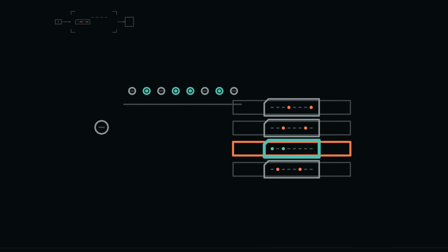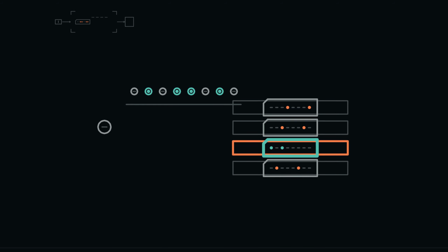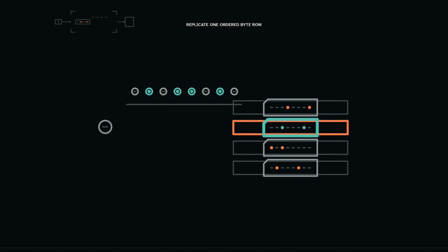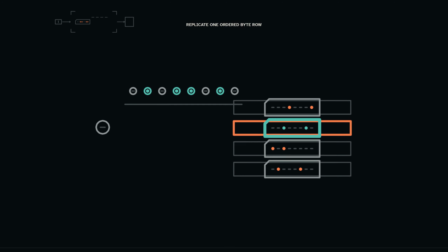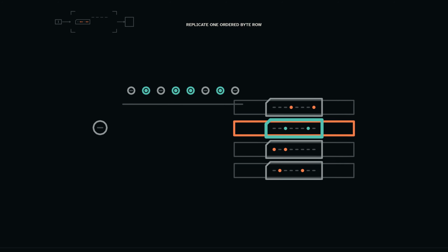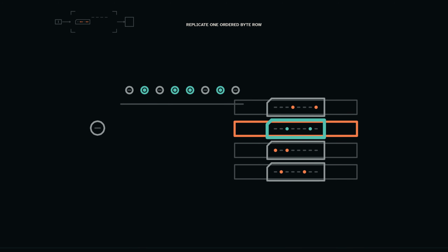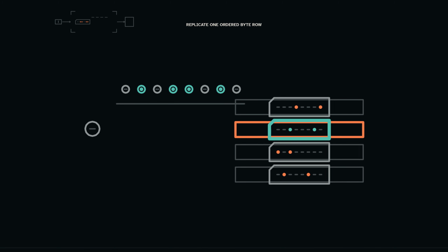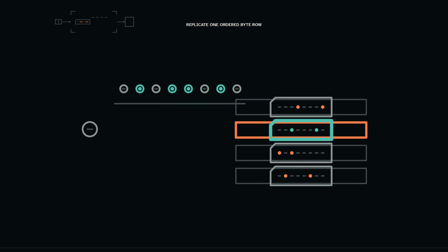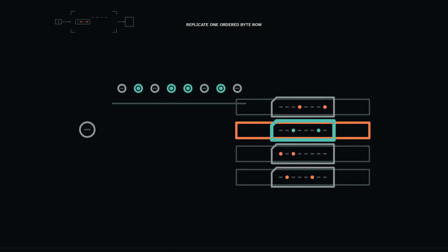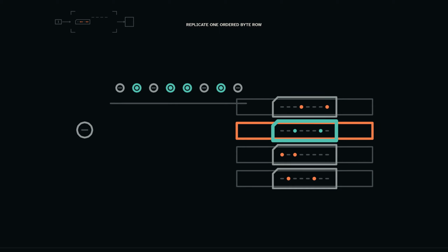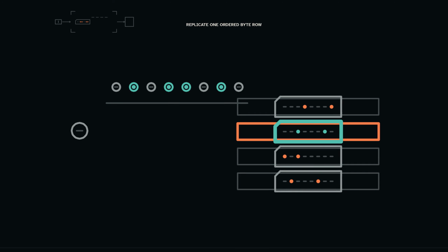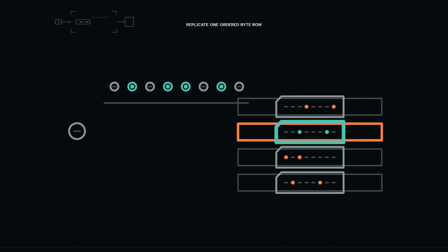The decoder did not move the data into row 3, it granted that row permission to capture the shared input while denying the others. Writing chooses which row may change. Reading chooses which stored row may influence the output. Hold the address on row 2. The output selection path connects row 2's 8 stored bits to the memory data output while every other row remains excluded. No row changes merely because it is read. This is like consulting one numbered drawer only in the limited sense that selection exposes one drawer's contents. The circuit does not open a physical drawer, and the output is a newly established signal representing the stored byte, not the original physical conditions leaving their cells.